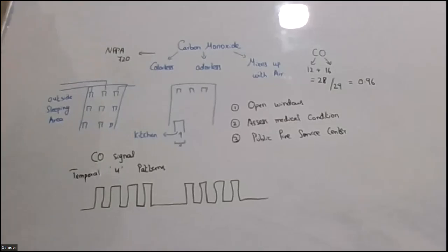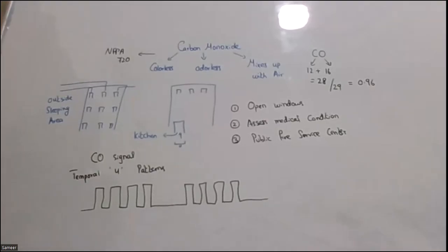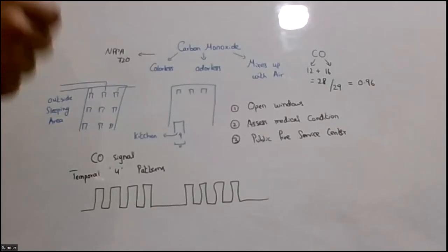So, sensitivity should never be reduced. And whenever we are testing our devices, we usually use testers, smoke testers. They create a type of mist or fumes inside the detectors to analyze the probability, that is, how reliable the system is going to be.